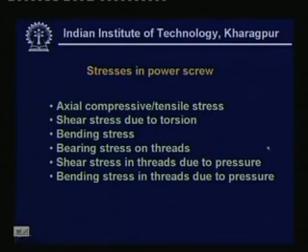Now, all of the stresses due to these last three criteria must be taken care of, and we will have to find out the equivalent stress. When you use the von Mises criterion you will have to find the equivalent normal stress, or if you want to use maximum shear stress then you will have to calculate the maximum shear stress. Everything depends upon the state of stress at different points.